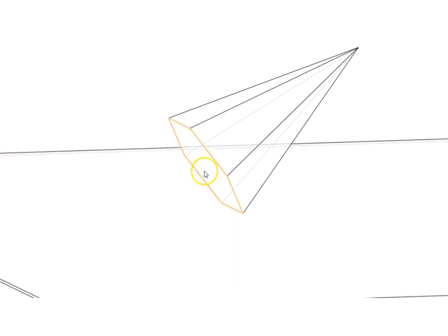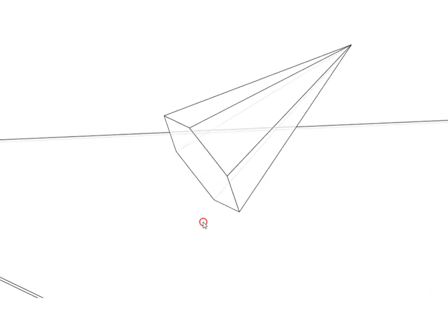One thing you can keep in mind is that if the axis of this pyramid is at a particular angle, the base will be at the complement of that. For example, if the axis is at 30 degrees with respect to the base, correspondingly the base would be at 60 degrees. The reason being the base and the axis are perpendicular. So this is one point you will have to keep in mind while constructing the solid.